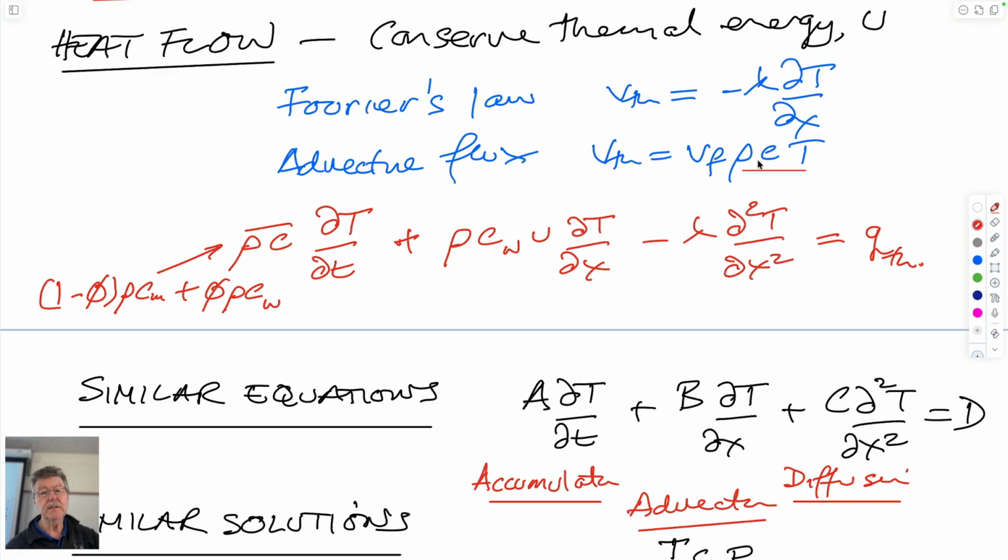The heat content is the density, specific heat capacity, and temperature. If you throw both of these into the conservation equation, you end up with a heat diffusion equation. Heat that travels by conduction, heat that travels by advection, in versus out in each of these terms,